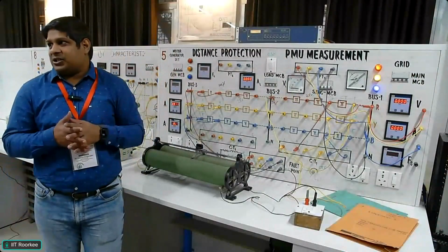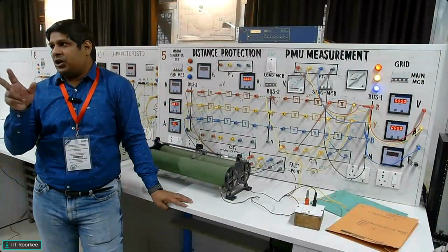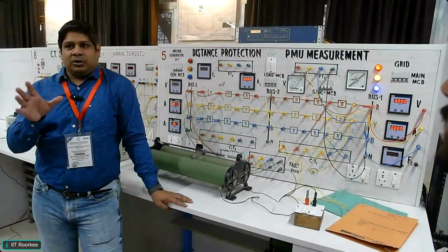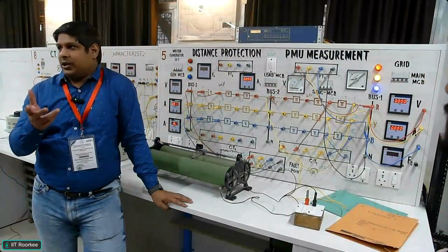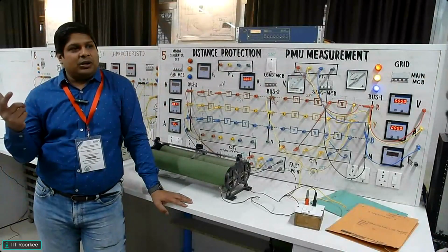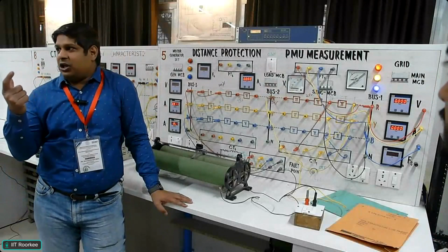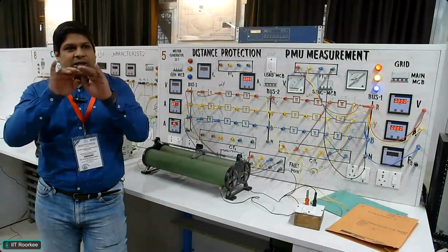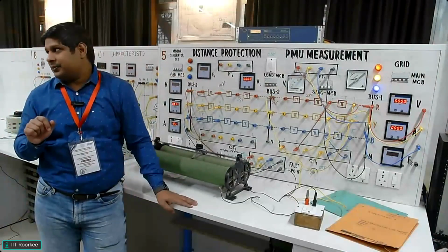You know pi sections in the medium transmission line: we usually use two types of models, the T model and the pi model. And usually the pi model has advantages over the T model. Why? Because in the pi model, we have fewer nodes. In the pi model, we have only 2 nodes, input and output. We have 2 capacitors and 1 RL in series. But in the T model, we have a node in the middle.